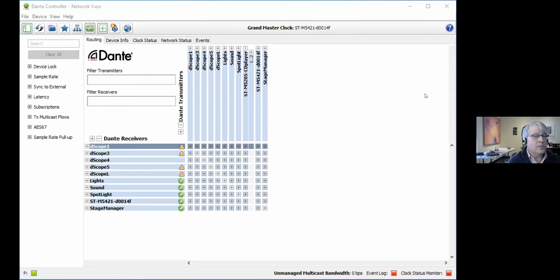Audio sends and receives. And what you have to remember, again, you'll get it quickly, is it's all 4-wire. It's all separate send and receive paths. So typically a console, just like your cables, you have an output and an input. In the terms of intercom, you no longer have a party line, you have an independent send and receive.